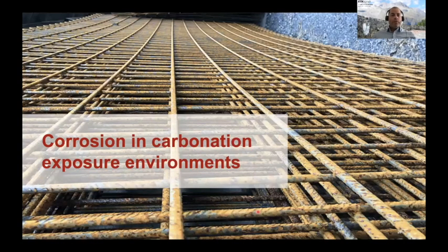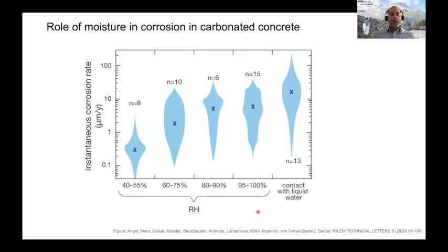After having reviewed briefly the state-of-the-art of chloride-induced corrosion in concrete, I would like to move on to carbonation-induced corrosion in concrete. Now, as I have already shown earlier, what is critical to get corrosion going in carbonated concrete is that we need a relatively high water content at the steel-concrete interface.